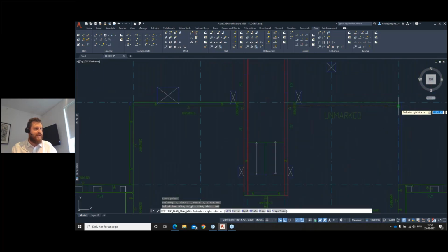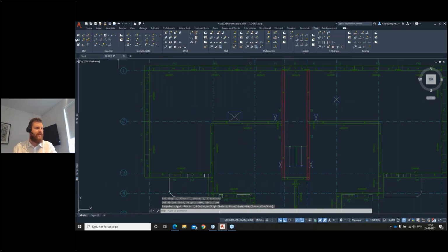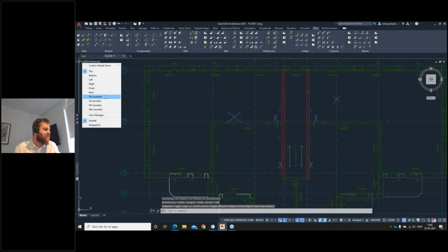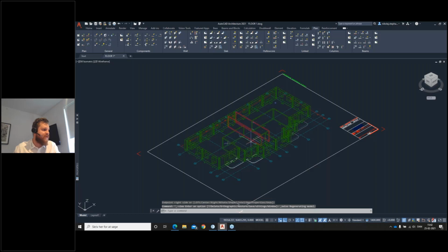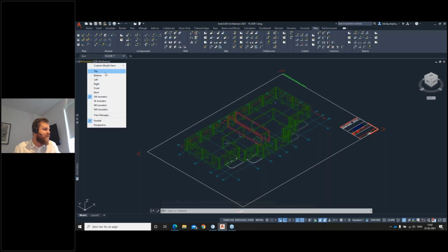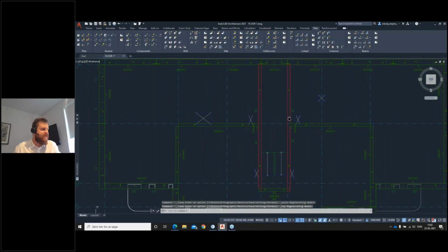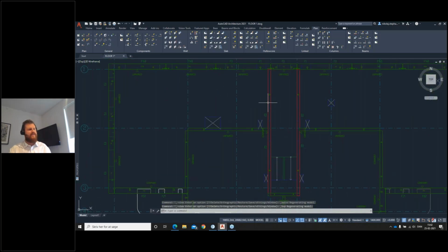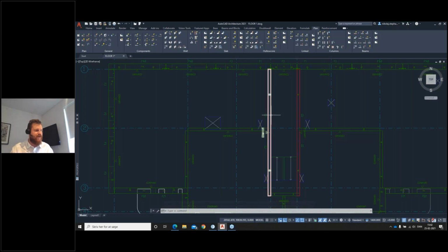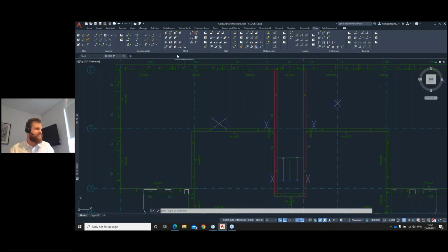So the same thing's happening here as what I did before with the sandwich panels, just with the solid walls instead. So you can see I've added them here. Some of them are red. The reason why they're red is because it says, well, you can't really make panels this big. If I hover the mouse over it, it says this has an invalid production length. Your factory, Nick, is not allowed to make solid walls more than 9 meters.